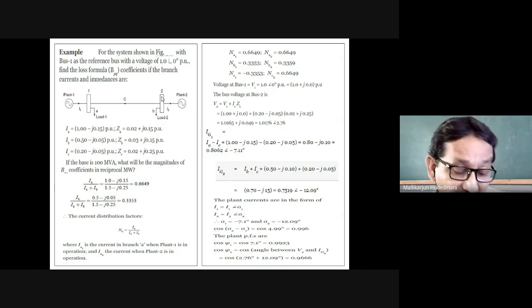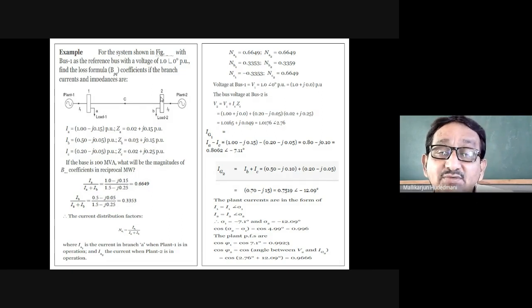When I want to calculate V11, V12, V22, I certainly require V1, V2, cos phi 1, cos phi 2, sigma 1, sigma 2, P1, P2, like those values. To get those values, I have to start from the given reference bus. What is the value of the second voltage? I have to calculate it by theory. Therefore V1 is said to be the reference, 1 angle 0. V2 is not mentioned. V2 is just a drop: V1 plus this drop gives V2. I have to keep it ready.